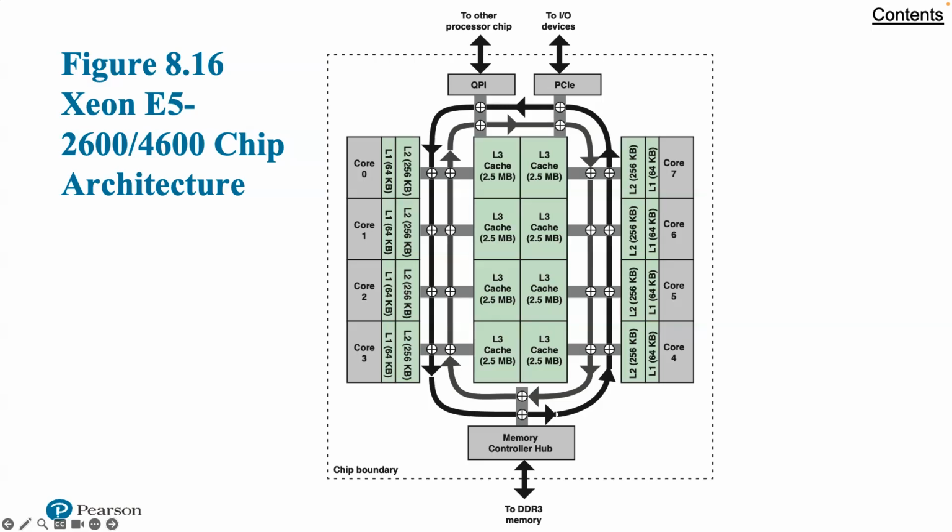The MCH must also invalidate any L3 cache lines corresponding to the updated memory locations. In this case, one or more off-chip memory writes are required. Further, if an application wants to access the new data, a main memory read is required. With the availability of large amounts of last level cache, a more efficient technique is possible and used by the Xeon E5